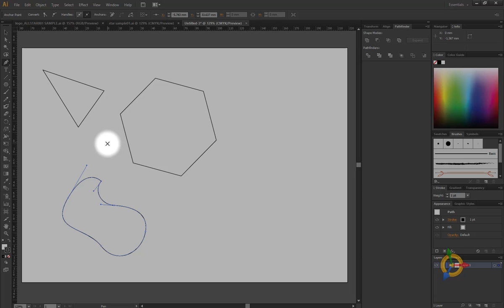Now what I'm hoping is that Maya will actually recognize that and therefore place these shapes around the origin just here. So these should be sort of above the grid and this one will be below. And it'll kind of be centered. This 0 point is the only thing that Maya will recognize. It doesn't care how big the document is out this way or how big it is down here. So let's see if this works.